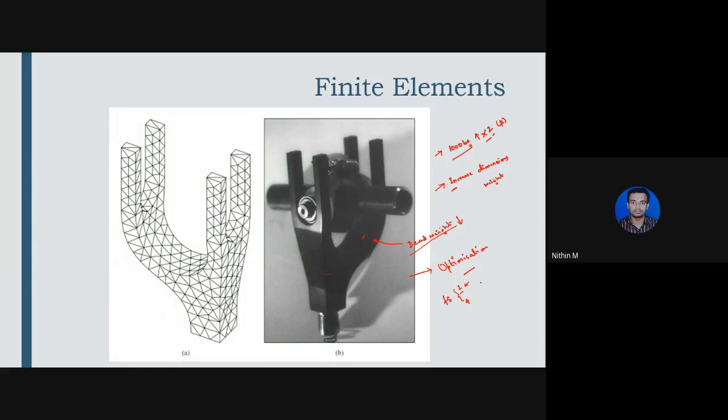So what is it that we need to do? We need to make sure that the factor of safety is almost equal to 1. This is what we call optimizing. So in optimization, we will judiciously and intelligently design a component such that it will not fail under any operating conditions, and still the factor of safety is almost equal to 1. Again, it is difficult to use exactly 1. It may be somewhere around 1.1, or it might even be around 1.01.